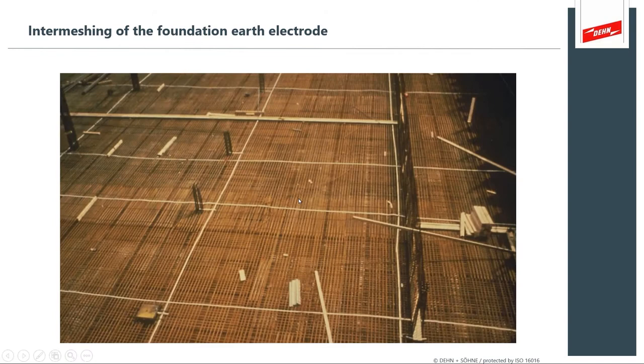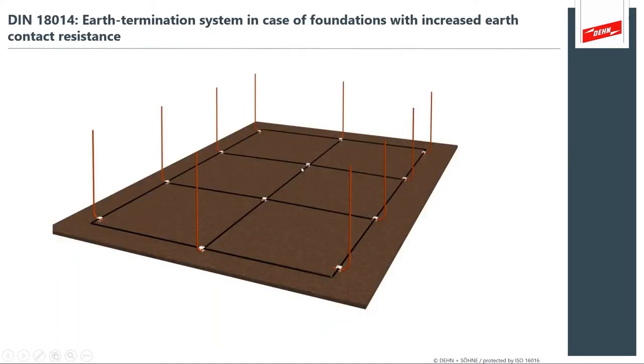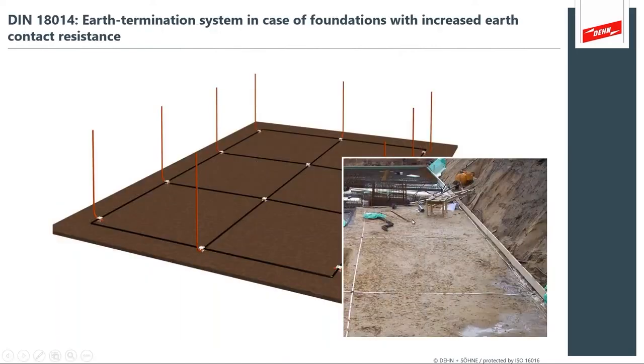So this is what it should look like during the construction phase, where you can see the rebars embedded in the flooring. We're looking for the interconnected mesh. You need to be able to identify these risers that will connect to the building steel at a later time, and this is all part of the design. This is what it looks like during the construction phase.